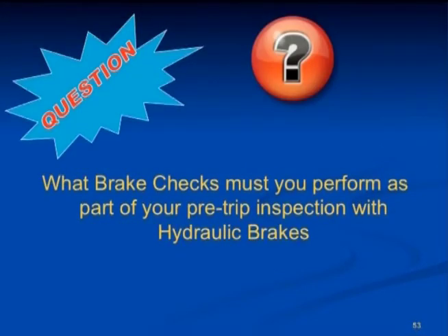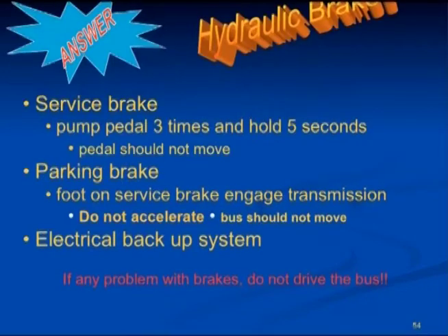What do you check when you do a pre-trip inspection with hydraulic brakes? With a service brake, pump the pedal 3 times and hold for 5 seconds. The pedal should not move. With the parking brake, have your foot on the service brake, engage the transmission, do not accelerate, and the bus should not move. With the engine off but the key in the on position, you should hear a humming sound, which would indicate an electrical backup system is operational. Again, if you have any problems with the brakes, do not drive the bus.